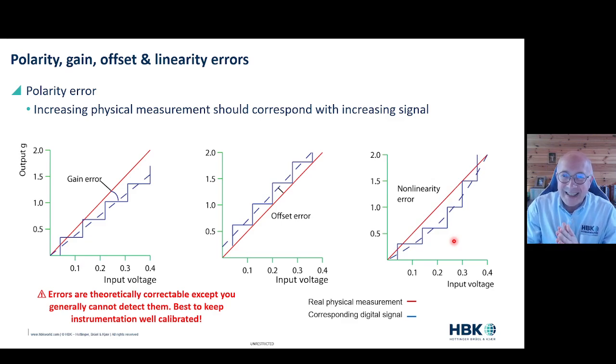The best way to get out of this is to spot what's happening and then take that channel in post-acquisition and multiply it by -1. You don't want to be taking apart all of your components and resoldering wires when all you need to do is multiply the signal by -1. So polarity errors do occur regularly, and it's just a matter of tracking them down before you go out and then correcting them in post-process later.